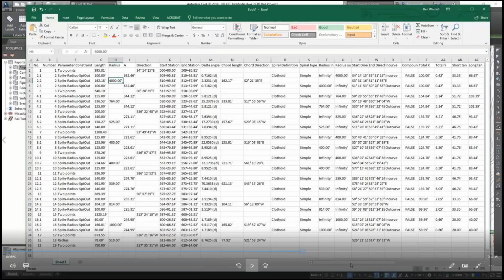Yeah, those are available as well. The reports that I'm showing in this demonstration are more for geometry tabs, but yes, those are available. There's a handful of different reports where you can do staking reports and offset reports and things like that. All those are available, particularly for when the surveyor is getting out of the field and has to stake the center line, things like that. A lot of this information can be pulled into that.